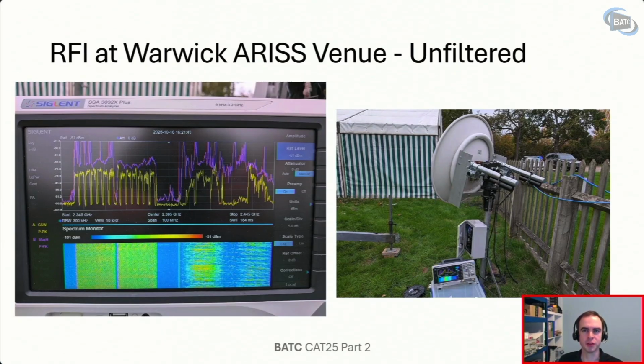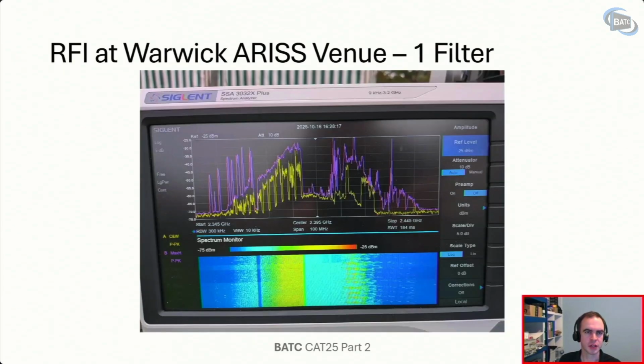A lot of this will probably be the Wi-Fi, as Jen mentioned, it's quite bursty. That adding to the power of the 4G adds together to make some high power bursts. So I put in the one filter, this is John's filter, the 5-pole John's filter, and you can see that that's rounded it off quite well. In practice, for the low elevation that I was trying to achieve at this location, this wasn't quite enough.